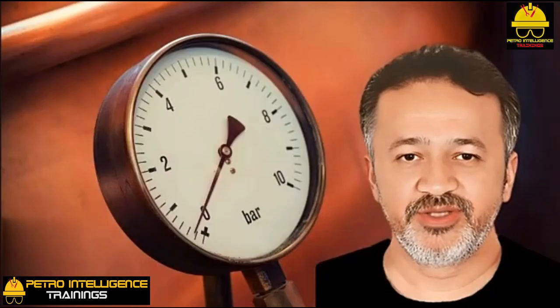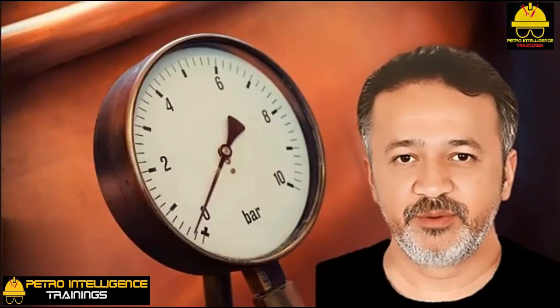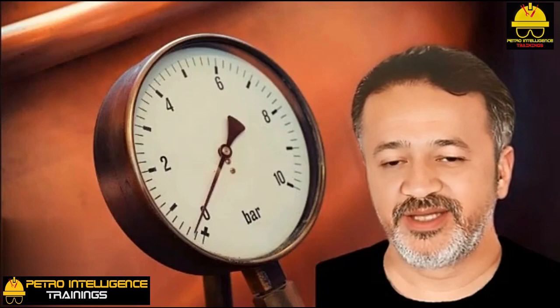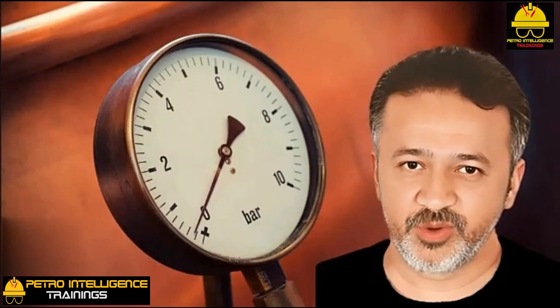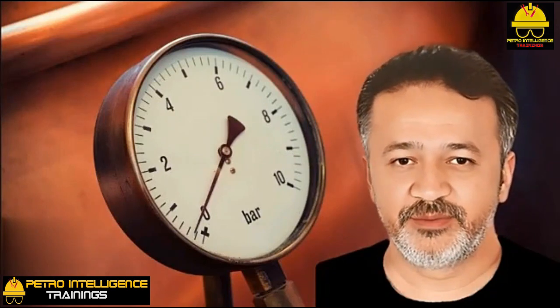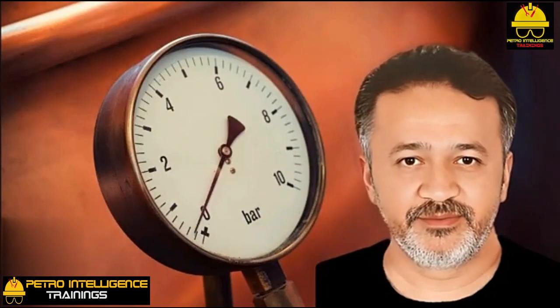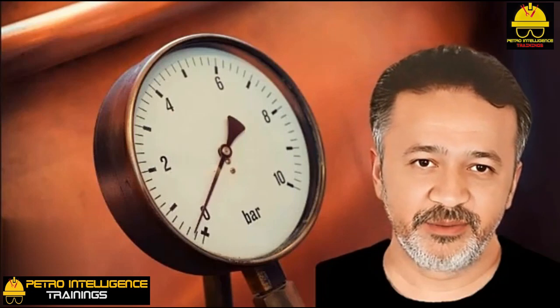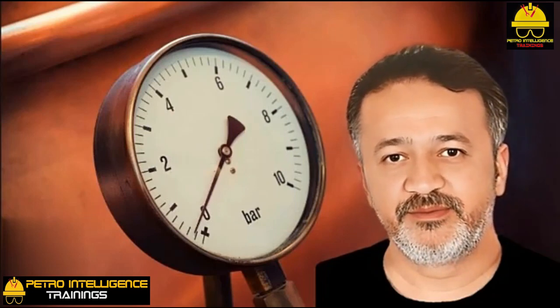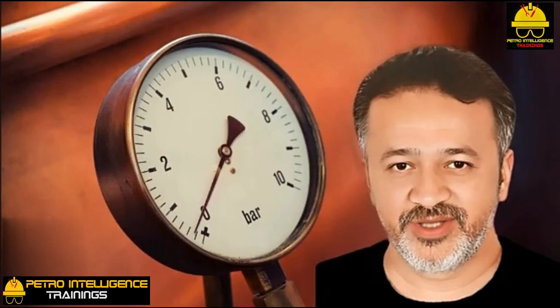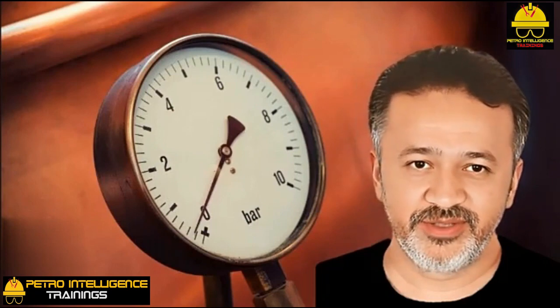Pressure transducers. Disassemble a pressure transducer, and you will see a small plastic diaphragm. A change in pressure distorts this diaphragm and generates a small electrical signal. The signal must be quite tiny, because placing your hand on the transducer can alter its reading. A modern digital pressure gauge uses a pressure transducer.